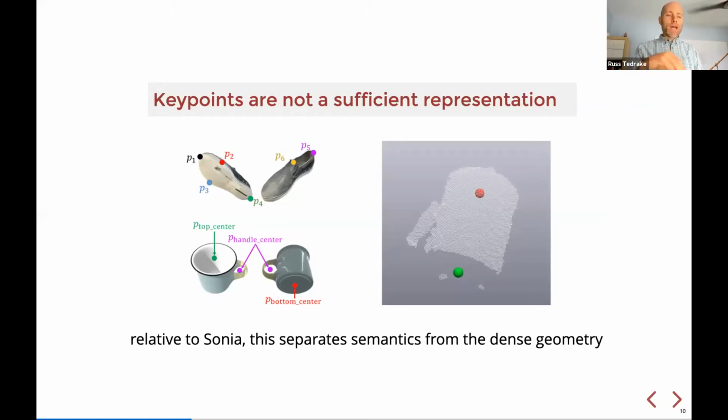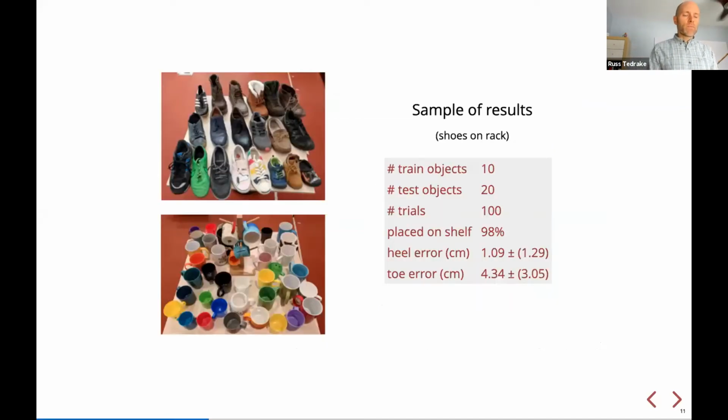But in order to grab the object and start moving it along that transform, we take a quick snapshot of the instantaneous point cloud, or we can use a dense reconstruction mechanism, to accomplish that entire manipulation task. So the key points are not a complete state representation, but used with the local sensing they give enough to do a wide variety of tasks.